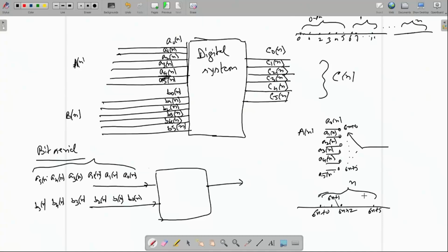So, you can view as though this data were coming parallelly, but I am using a commutator kind of thing, just running through, I am tapping them one after another at a very faster rate, 6 times faster rate, and whatever coming they are sending you down the line. So, each bit comes down through a very narrow clock pulse, 6 times narrow, or in terms of speed 6 times faster. That is same for A, same for B.